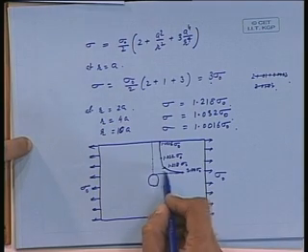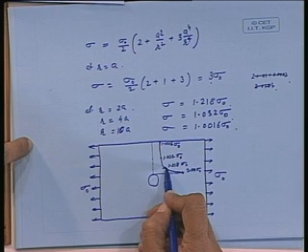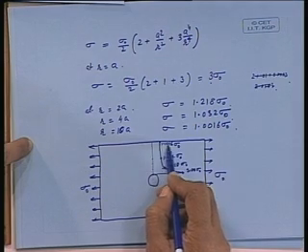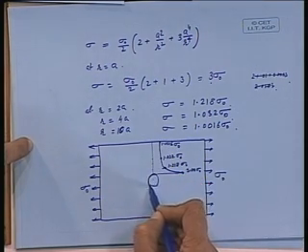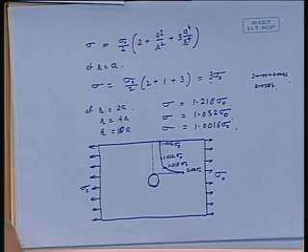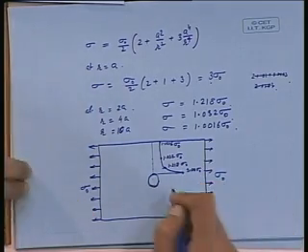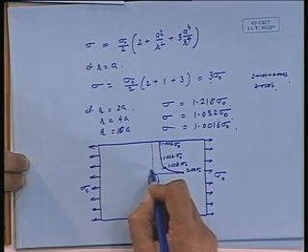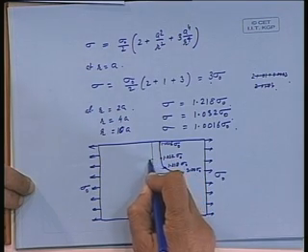So you see in the vicinity, this is 200% more, this is 22% more, this is 3% more, and of course this is only 0.16% more here, just because some material is not available. Some increase will be there because they have to share it. This material is missing, but you see who shares the maximum is in this vicinity. So the concentration of the stresses is around this area.